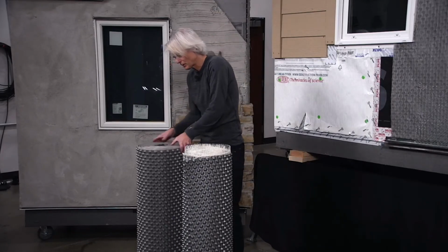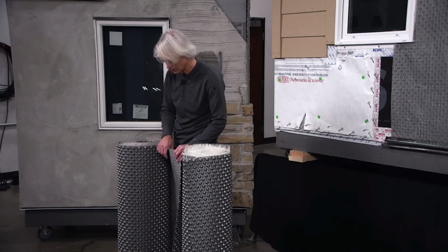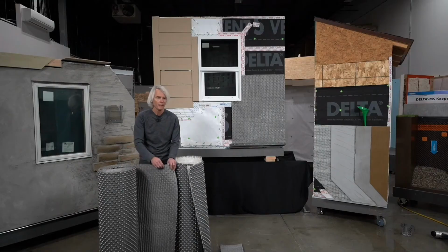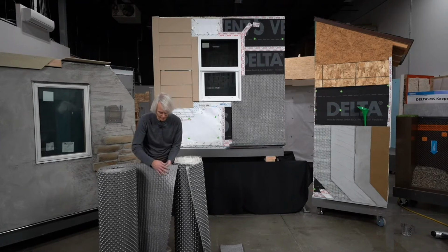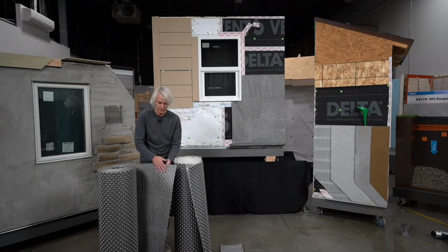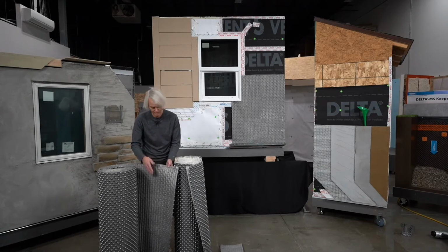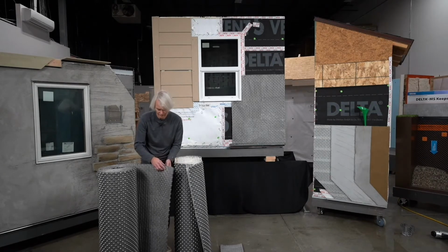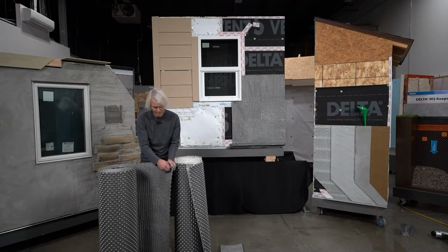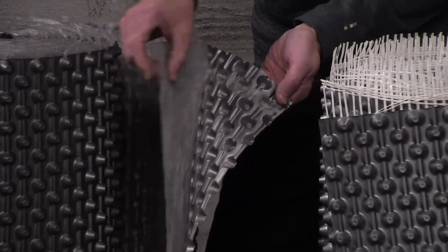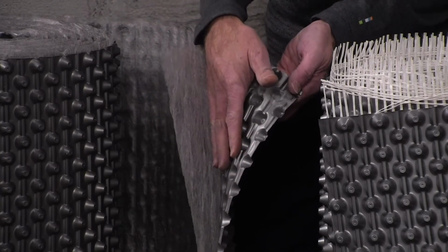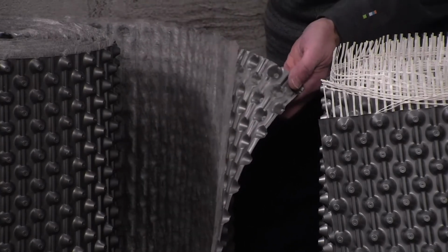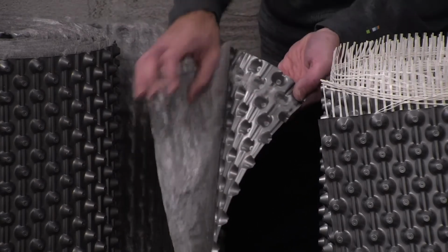This one, the first product that we showed on the wall, has this receiver sheet on the front. What that facilitates is not using basically an asphalt or grade D paper on it, and the lath can go right on top of it. So this was a generation that sped up that process. It didn't require another layer on it. Of course, we have lath there, but this product is also available without this fiberglass sheet on the front, and you can just install a standard grade D paper and lath over it as well. So grade D lath and paper can be put over the raw product.